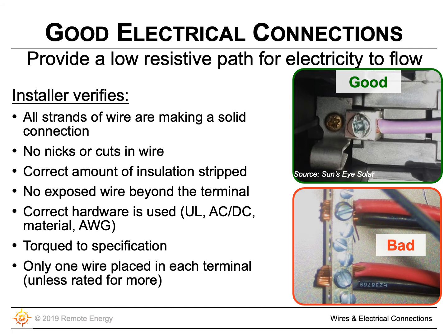Now I said take the insulation off because if you don't do that, if you just strip a little bit of insulation so there's only a little copper showing, and you push that into your set screw connection, maybe you're actually setting the screw on the plastic insulation and not the copper. So strip it correctly and get the correct amount of copper under the lug.